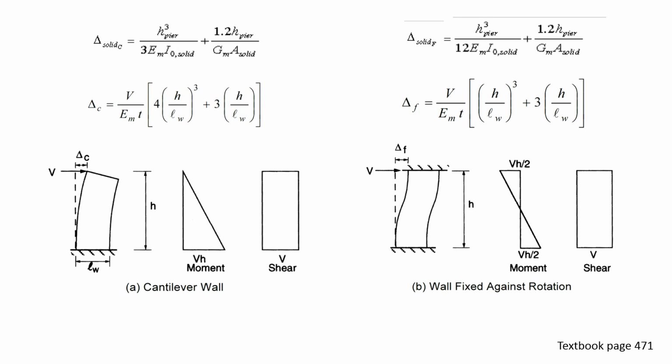So how do you decide whether the top of a pier is fixed or not? This is the million-dollar question, and if there were consensus guidelines, then MASS would be able to take care of this for you. Unfortunately, there are no clear-cut guidelines for what counts as fixed and what counts as being cantilever. So it actually ends up being up to the discretion of the designer to model this behavior as he or she sees fit.